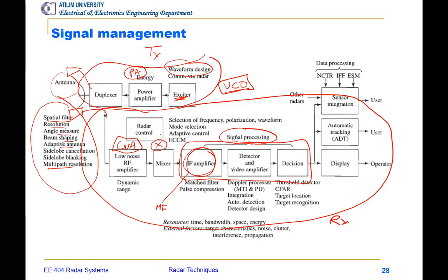There was a mixer that we used, and this VCO was connected to this mixer, using an attenuator right here to balance the power from the LNA and the VCO. And then we got a low pass filter here in laboratory, the modular radar we used in laboratory. And then we look at the output of the LPF using a spectrum analyzer. Now, in reality, of course, we got IF amplifier, detector, decision stage, and then display.